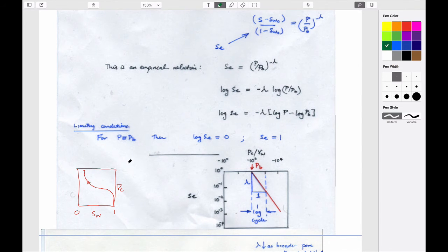We know that we could, for instance, adulterate this figure by plotting it in terms of saturation of water. We could plot it in terms of volumetric moisture content, the volume of water divided by the volume of the voids. So our definition is volumetric moisture content, MC. We know that when it's got no water in it, in terms of saturation, the volumetric moisture content must be 0. We know when it's 100% saturated, do we know what the volumetric moisture content has to be, the upper limit?